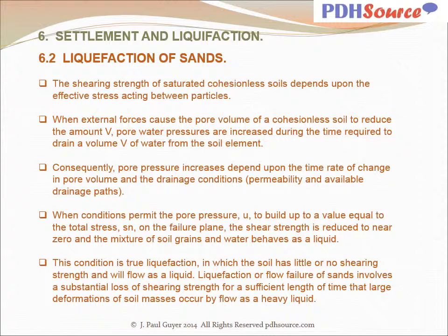available drainage paths. When conditions permit the pore pressure to build up to a value equal to the total stress on the failure plane, the shear strength is reduced to near zero and the mixture of soil grains and water behaves as a liquid. This condition is true liquefaction, in which the soil has little or no shearing strength and will flow as a liquid. Liquefaction or flow failure of sands involves a substantial loss of shearing strength for a significant length of time that large deformations of soil masses occur by flow as a heavy liquid.